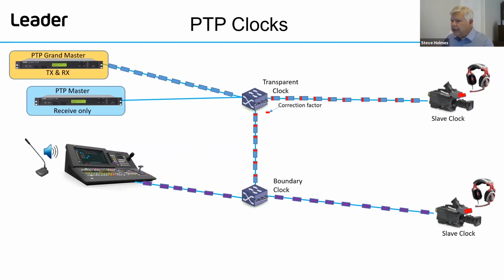But the communication for delay request, delay response, all of the syncing will be done just from that boundary clock out to the slaves that are out in the network. And then the secondary PTP device will be listening to all the messaging that the Grandmaster is putting out to know when he should step in or shouldn't, and the pecking order of who does what when.